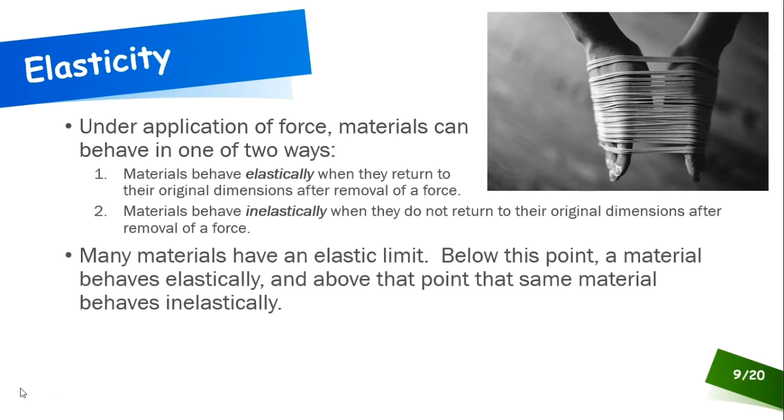Now, as I was just saying, many materials have what's called an elastic limit. So as long as the stress or the force that you have imparted to the material is below that elastic limit, then you can apply the force, the material will stretch out or deform, and then when you let go of the force, the material will return back to its original dimensions. And there will be no permanent deformation in the material. But if you exceed the elastic limit, you're going to introduce permanent deformation in the material once you release the force.